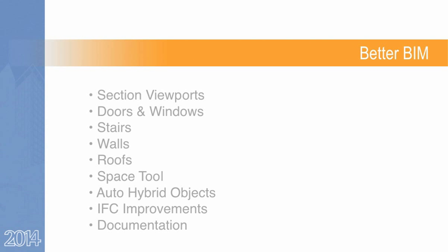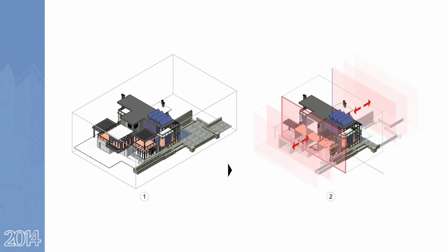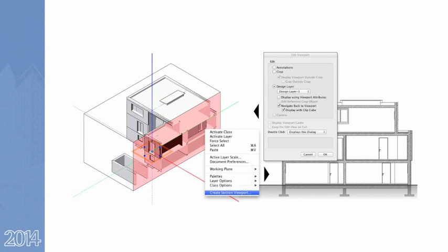We've broken the new features into several categories, starting with section viewports. The first is Create Section Viewport from Clip Cube. The Clip Cube has moved beyond its previous role as a visualization tool and into being an excellent interface from which sections can be quickly and accurately created.